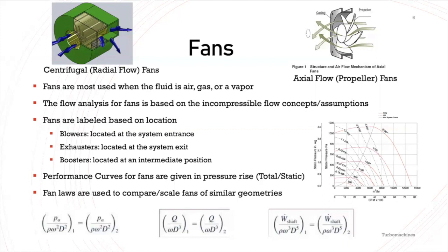Performance curves for fans are given in a pressure rise graph, either total or static pressure, rather than head rise typically used for pumps. And fan laws shown below are used to compare and scale fans of similar geometries.